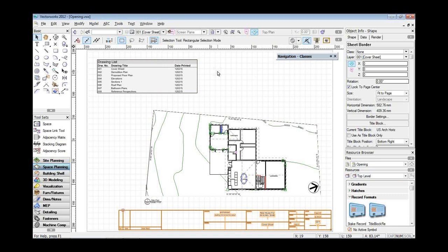The way that it works is it creates a three-dimensional path, a NURBS curve. You then attach a camera to it, and then you basically tell it to fly along the path. You can have several cameras on the path, and you can transition from one camera to the other. And you can even make things open and close.